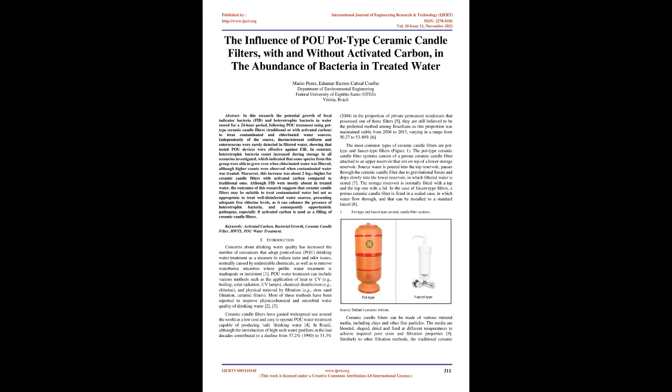To prevent biofilm formation within the candle itself, some ceramic candle filter producers develop new candles with colloidal silver impregnated on their surface or mixed with the media before firing. One of the main advantages of POU ceramic candle filters is that they do not require energy supply and, therefore, they are an attractive alternative for remote rural communities. In contrast, the major risks to the success of all forms of ceramic filtration are hairline cracks and cross-contamination. Even the presence of only a slightly cracked filter can make it unsuitable for reduction of particles and microbes from water.